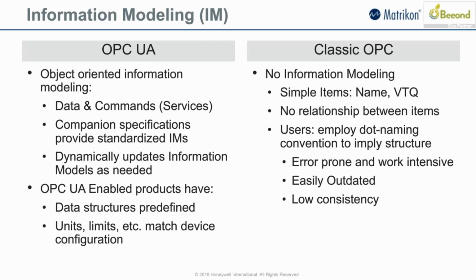So everybody in that industry can then use that one companion specification, which is publicly available, so that everybody describes a valve, or an actuator, or whatever the piece of equipment is, as long as, let's say, it can be standardized, or a standard already exists in that specialized field. That standard can now be translated into OPC UA information modeling, and regular OPC UA servers can read that information model in, and they can work with it.